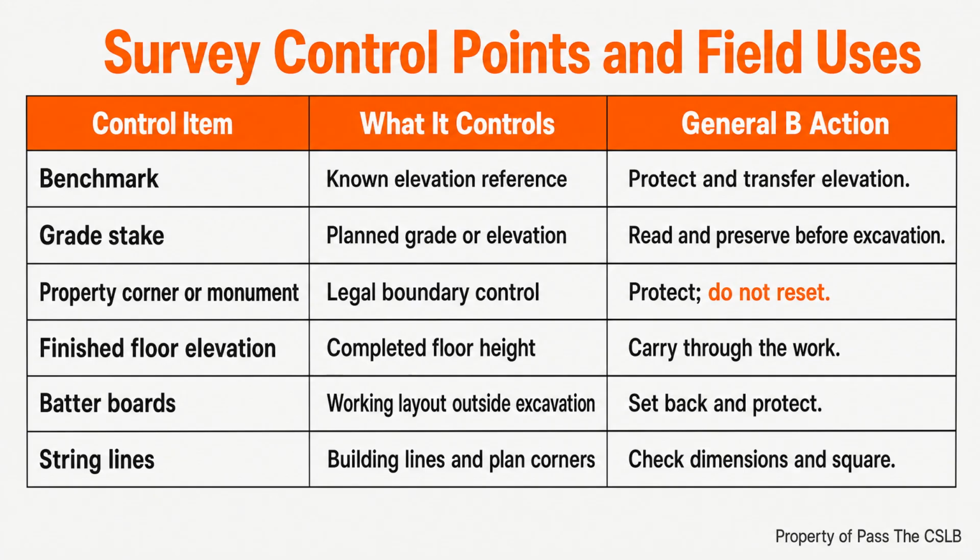Imagine a contractor replacing a driveway and adjacent sidewalk. A machine operator reaches a small brass disc that lies directly in the demolition path. The safe supervision decision is to stop that immediate work, protect the area, and coordinate the required survey reference before removal. The contractor should not photograph the disc, measure from a fence, remove it, and assume those notes are enough to recreate a legal monument later.